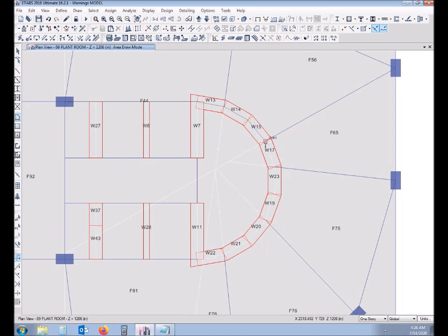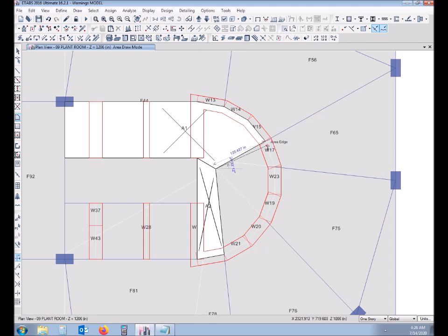It's better to do it in parts if it's still giving the error of area load transfer. You could have assigned it individually on each part of the slab which is an opening here. But it was important to match the slab on the beams.